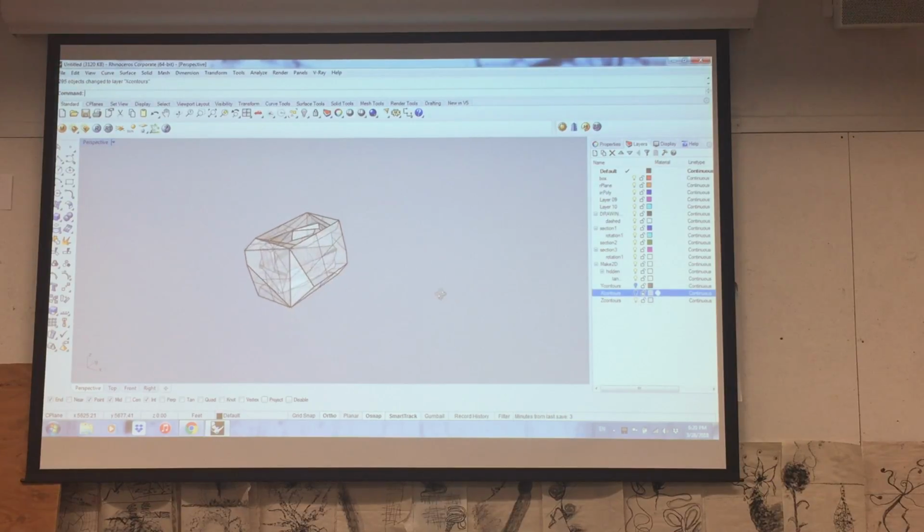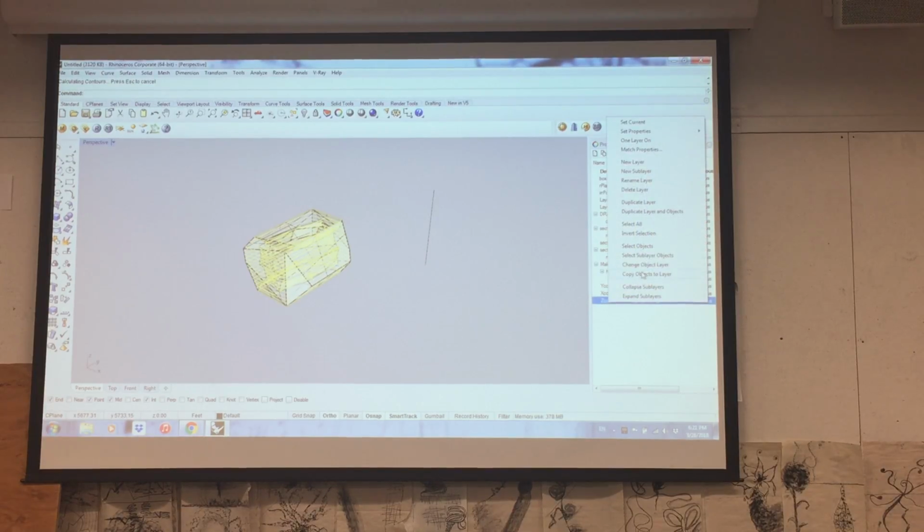And then for the Z contours, I don't have a reliable straight up and down line that I can reference, but I can draw one. I can draw this polyline, and I can rotate it straight up. Right, so I have a straight up line. And now, when I do contour for the 3rd time, I can snap to these points to make sure that my contour vector is actually in the Z-axis. I have 2 feet between, and I hit enter. There's all my Z cuts. And I'll put that on my Z contour layer.